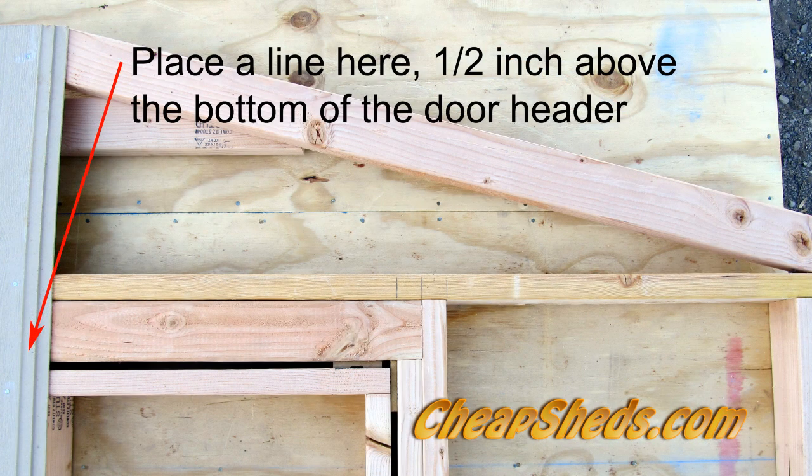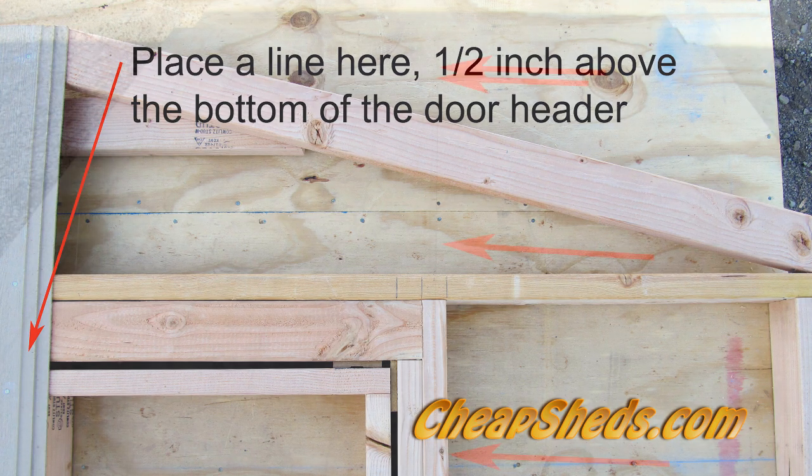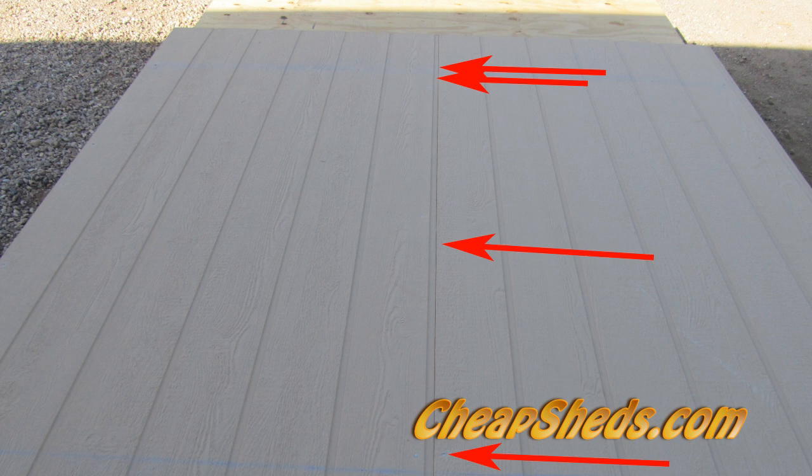Place a mark on the siding 1/2 inch above the bottom edge of the header. Make sure this mark is visible when the second piece of siding is installed. Lay the next piece of siding in place and put 4 nails in to match the nails in the first piece of siding. Then check the bottom overhang and put a nail into the outer ends of the top and bottom plates.